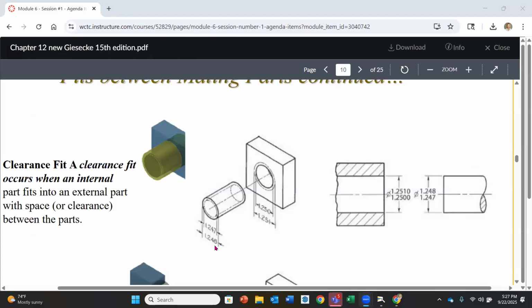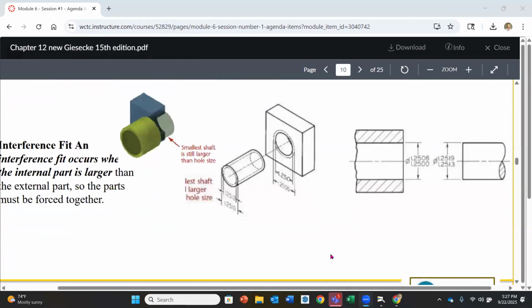Okay, good. Now down here, let's look at the values that we see here. You're going to notice in this case, oh no, it's not the same size hole. We have 1.250 to 1.2506. My goodness, 6/10 of a thousandth. That's starting to now probably get into maybe doing a little bit of reaming, I think. Which again, takes more time, energy, and tooling. So it's going to be more costly, but that's okay.